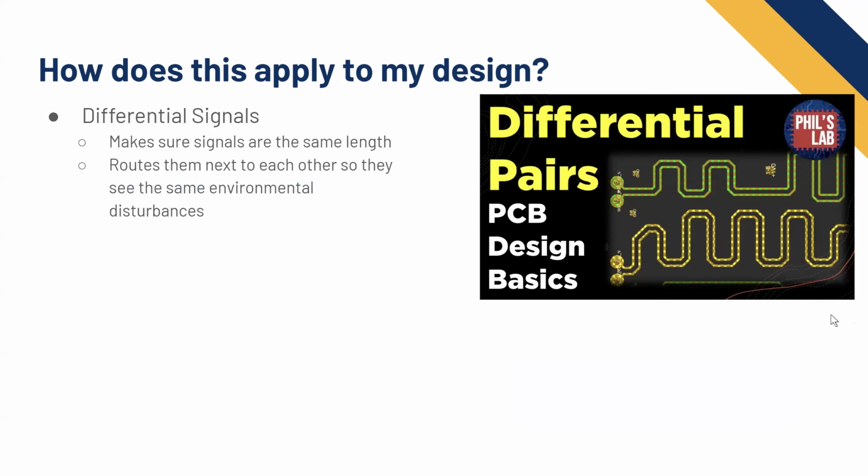Oh, last one. Differential pairs. I just want to make sure that everybody knows that there is a differential routing tool in Altium, and to make sure to use this tool when you route your CAN traces or any other differential traces. You basically right-click the normal routing tool, and then you just click the differential routing tool. And it requires that you defined them as differential pairs in your schematic, which, once again, when you have to define the CAN traces, we'll explain that. But everybody on the team should know how to do that. This is new knowledge we've been spreading within the team.